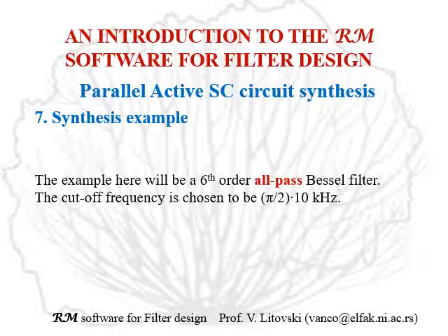When I'm saying the cutoff frequency, that is what was used for the synthesis of the low-pass prototype, which was used to create the all-pass filter by adding the transmission zeros, which are mirrored against the omega axis.